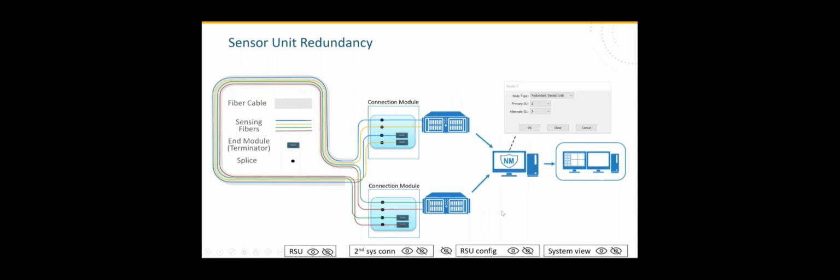Put, in this case, a dedicated network manager server in place, which can also be made redundant if the criticality concerns lead to that solution. And configure in there this virtual sensor that we've created that is the redundant sensor unit. So basically, the redundant sensor unit will attach to two physical sensor units and sort out the alarm management.